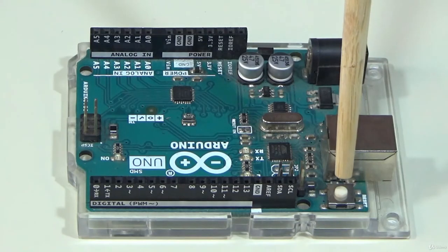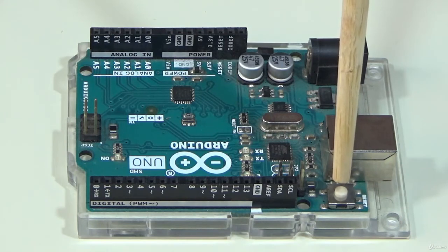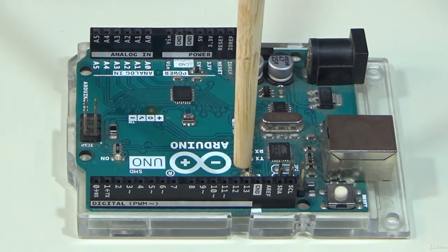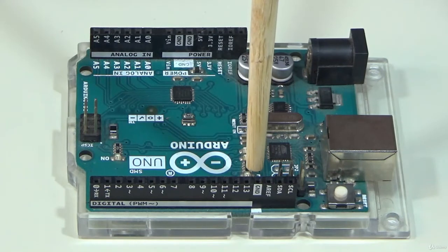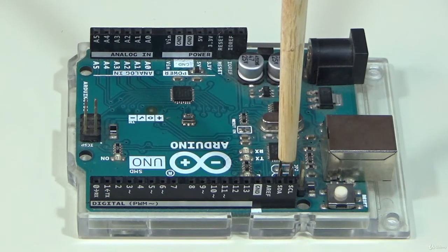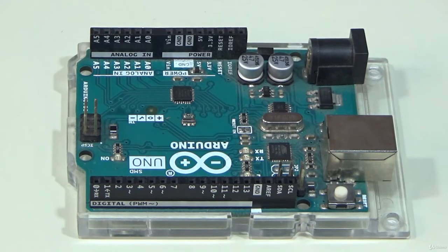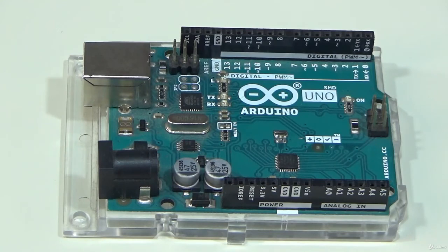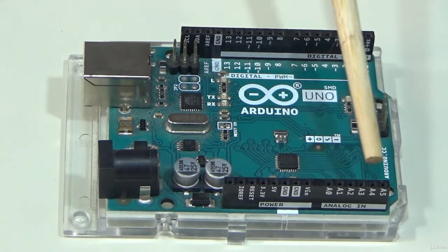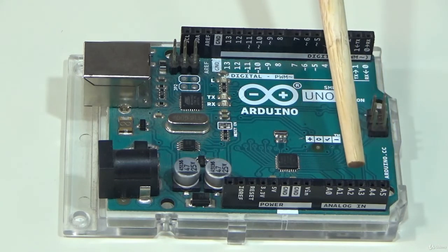In this angle, this is the reset switch. Through this we can restart the microcontroller, and these are the GPIO pins starting from 0 to 13. Then after 13 this is ground, this is analog reference, and these pins are for I2C communication, SDA, SCL. In this angle, these pins are for analog inputs starting from A0 to A5,